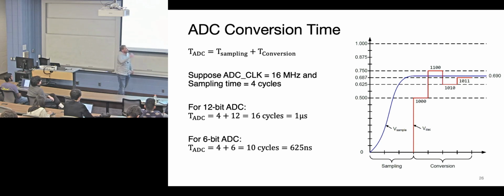There's also a point where you have to convert and you actually still have to get the data out of the SAR ADC and put it somewhere. That can have some overhead. There's a mechanism called DMA, Direct Memory Access controller, something like that. Basically, it's a tiny little core that only does very simple things. It just takes data from one location and puts it in another location.